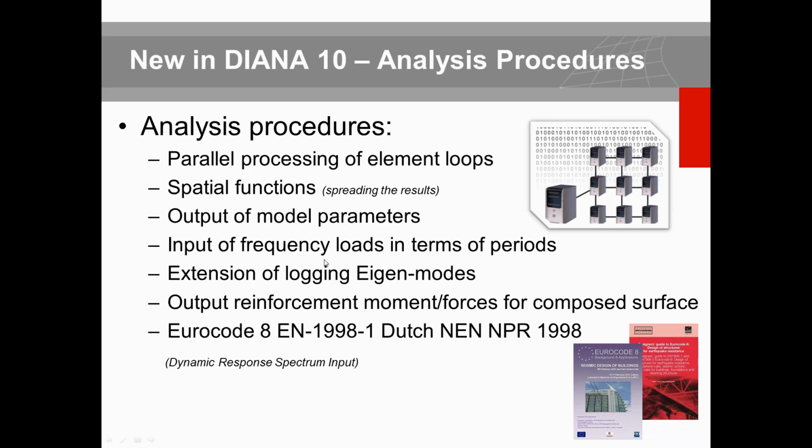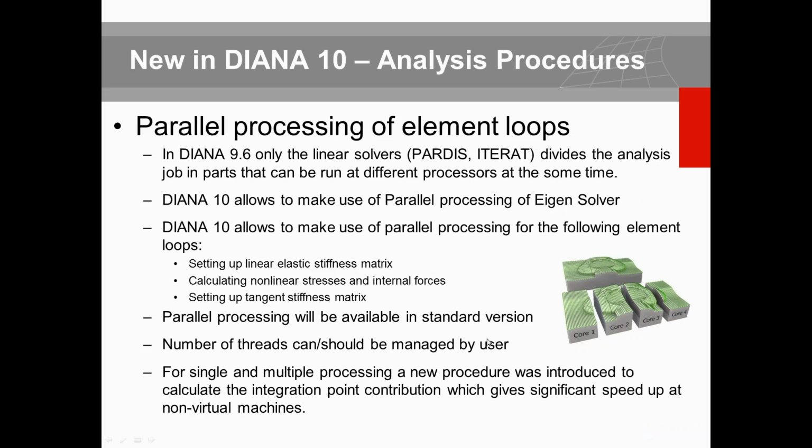Then we have a new input for frequency in terms of period. We have an extension of the logging for eigenmode. We also have a separate output for reinforcement representing the moment and force resulting from the reinforcement. And indeed, we have a dynamic response spectrum input based on the Eurocode and the Dutch NEN that are related to earthquake and seismic analysis.